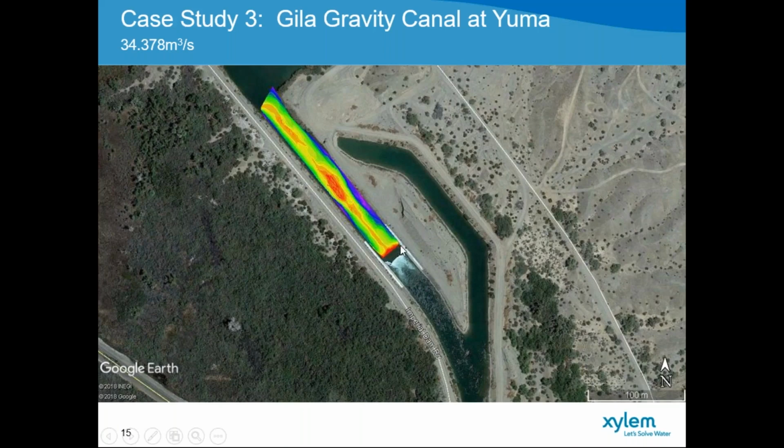So during the bathymetry survey using RiverSurveyor, we also performed velocity measurements. So this is a velocity contour plot in the channel itself. Here you can see the velocity distribution upstream of this, and then you get an acceleration across where the shallow portion is, or where the actual cofferdam was located. Then you get a reduction in velocity and even very slow negative velocities on the edges due to the deeper pool that's present downstream of it, and then again an acceleration right at the notch of the gauging weir.